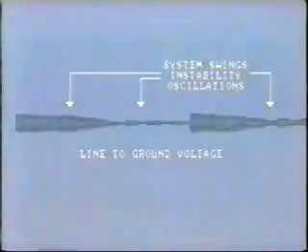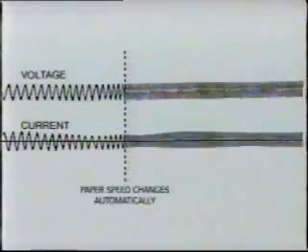Generally, the whole story can be shown within a few cycles, usually less than 1 second. System swings, such as those associated with instability, can also be recorded, but such swings may last for several hundreds of cycles and consequently give us a lot of paper to examine. Some oscillographs have the ability to change paper speed automatically when recording these longer-term swings.